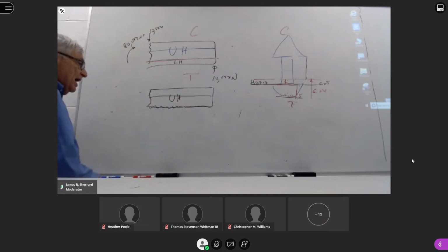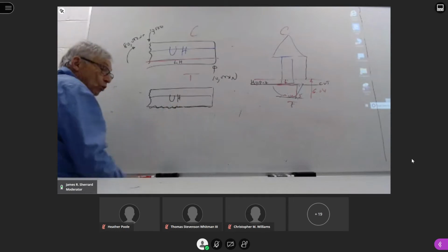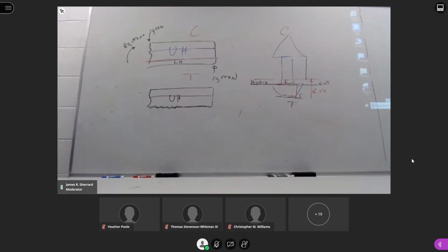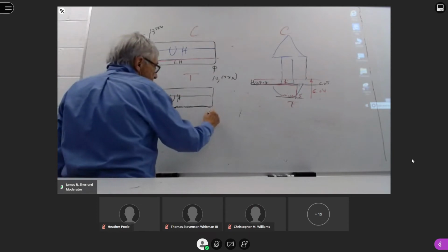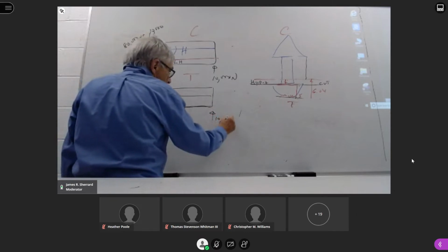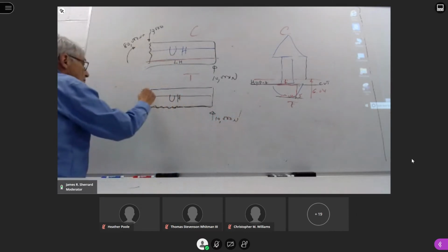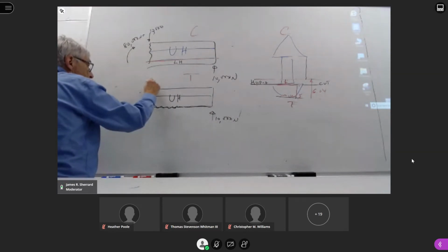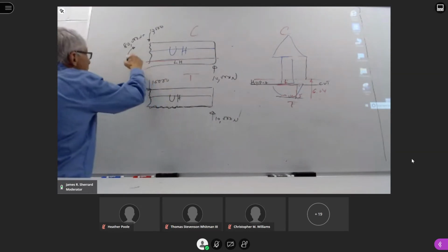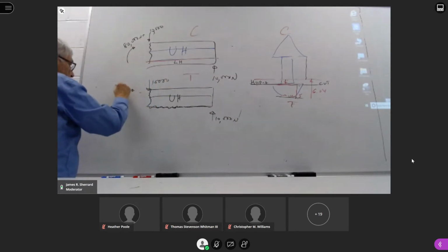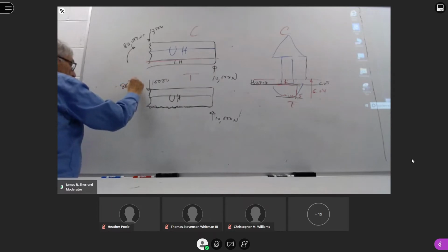In this case, when I cut it, I have one attachment point. So I know whatever I have to put in for forces, moments, torques, couples, I can only add at that attachment point. So when we do the free body diagram, we put in whatever we have for forces, moments, torques, couples. Okay.